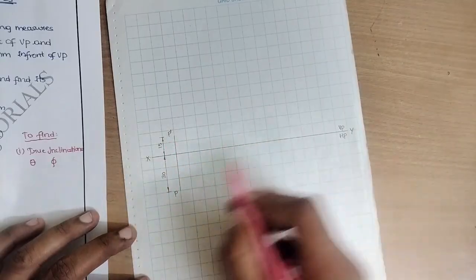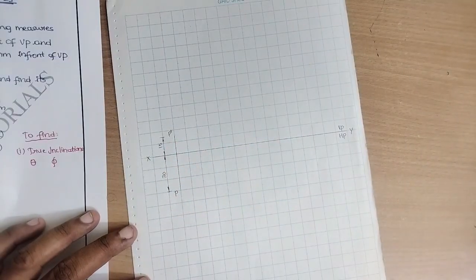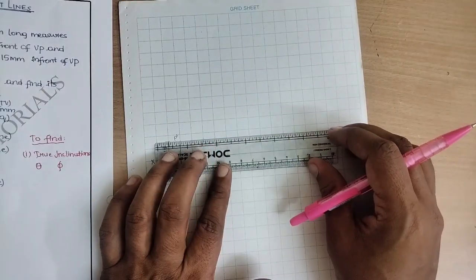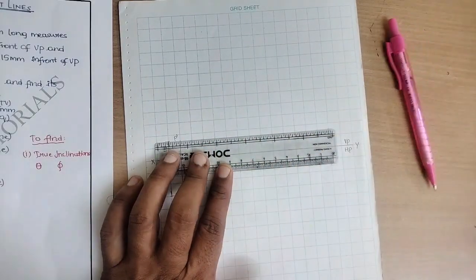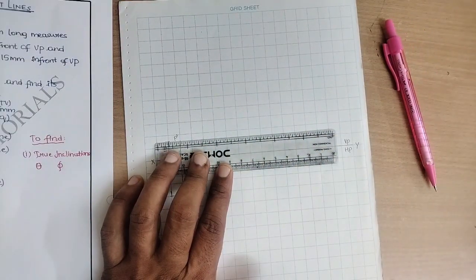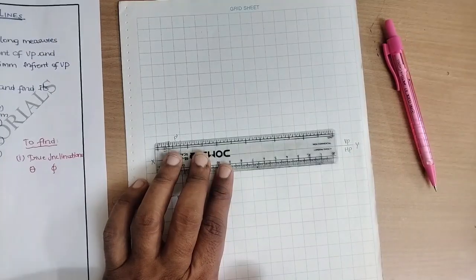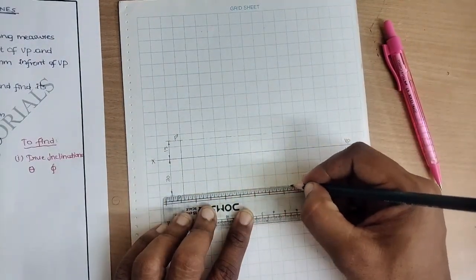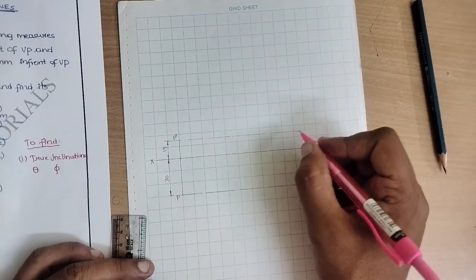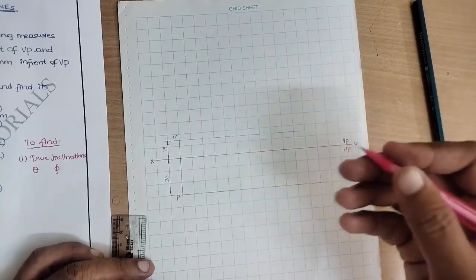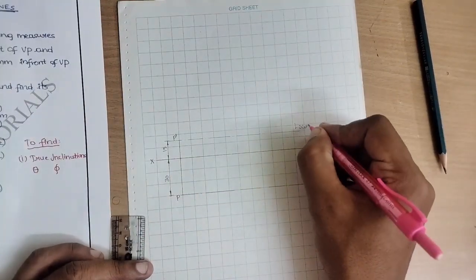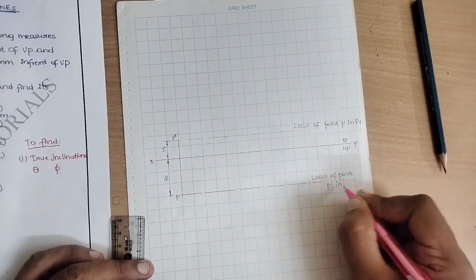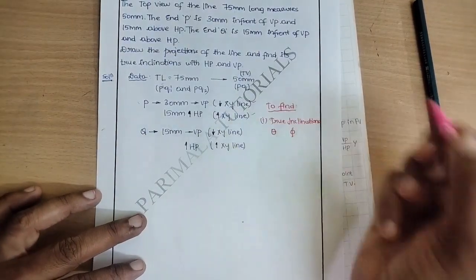Now don't you think we have got two endpoints? That is nothing but we have got two new loci. Draw a locus line representation. Locus line representation is an imaginary line, and its thickness should be minimum. I will mark this line as the locus line of point P in the front view and the top view. We have considered these two data as of now.